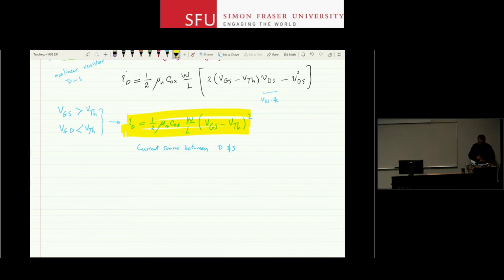Now, this is a MOSFET, and you can imagine that the P MOSFET looks like this, but instead of having N doping for the drain and source and a P substrate, I switch all the polarities. I will start with an N substrate and create two P regions for the drain and source, and I get my complementary structure as a P-type MOSFET. The N MOSFET means the channel is N-type. N-type MOSFET, N-channel MOSFET. P-type means that the channel is P-type.